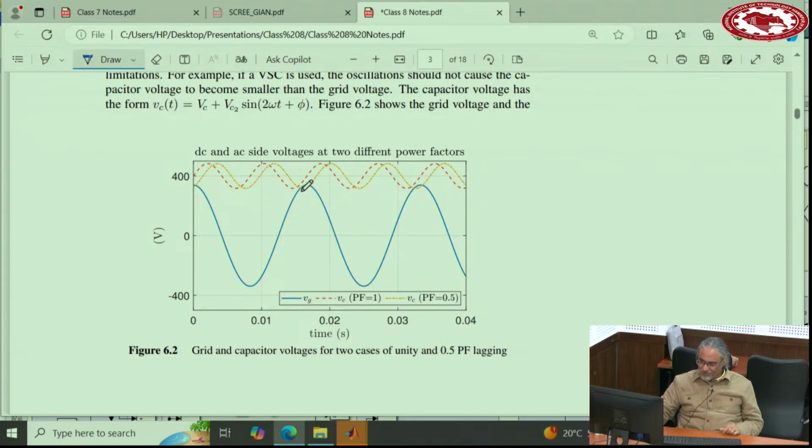So it could be at points that really goes below this one. So at least for this requirement, we have to make sure that the capacitor is sufficiently large. And often in practice, there are other entities which may benefit from that DC voltage, so you don't want to have large ripples across that voltage.